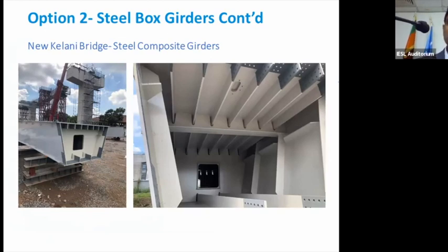You see a certain number of stiffeners are there, because the stiffeners are required in order to prevent plate buckling, right? Also the workmanship is very important, especially when it comes to detailing. And in the contractual stage, you need to put a lot of effort into monitoring the workmanship, because there is a lot of welding involved. So you need to provide high provisions, high inspection standards, and so on. Only then do you get the right product, and also the painting system.